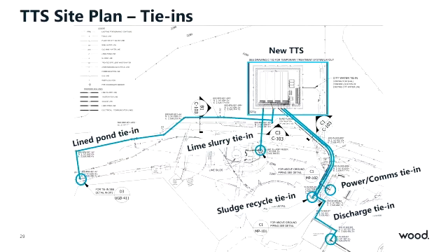The key sludge tie-in back here, all the way back on the other side of the aeration basin, to get sludge over into our process. Again, that way we could isolate this whole aeration basin and open it up for demolition. And then we had discharge that we needed to bring back into the clarifier that we routed out of the way of the construction. Used the existing MCC with just a 200 amp feeder cable that we brought over to the temporary treatment system.